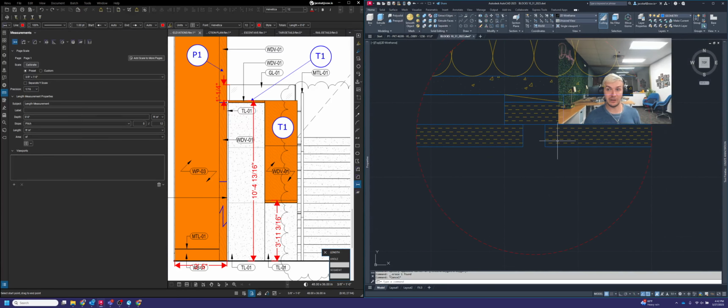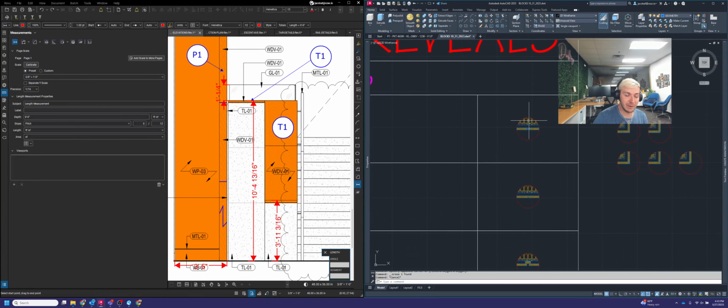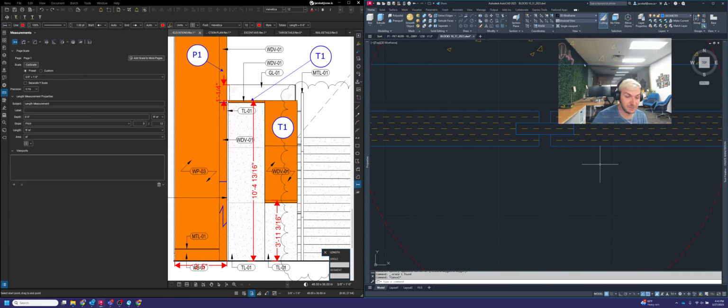This is a full depth reveal represented between two panels. But what it really is, you have a block of material 3/4 thick with shim behind it, and that block sits behind your panel. This is your panel here, and that block's going to sit right behind that panel. It gets attached to the wall, and then when your panels are seen, if you're standing in the room and you're looking at those panels, you're going to see the gap here as a finished block of material rather than the drywall behind there. So we do need a full depth reveal at the top of our panels, but in between any panel here, we're going to represent that reveal with a 1/4 inch spline reveal.